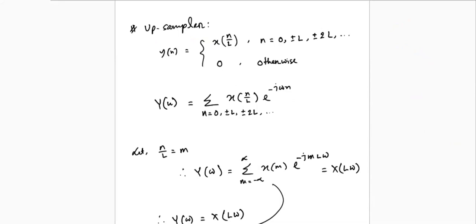Now, if we think about what actually happens in the frequency domain: in the time domain, we can think of the frequency as decreasing or increasing. But when a lot of sequences are combined together, you definitely need to understand what will happen in the frequency domain. So our main objective of this section is to understand properly what will happen in the frequency domain after doing the upsampling.